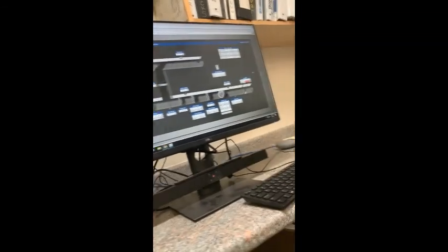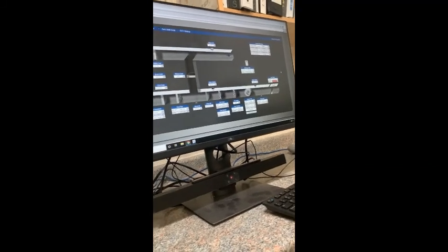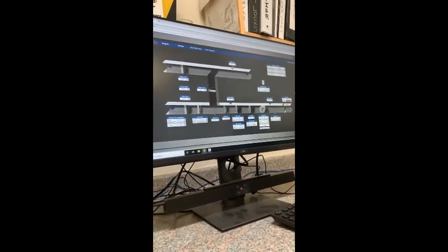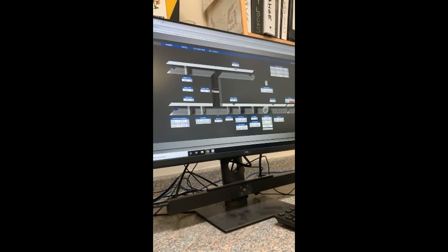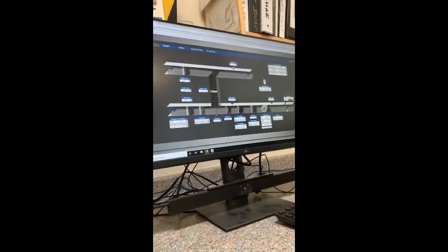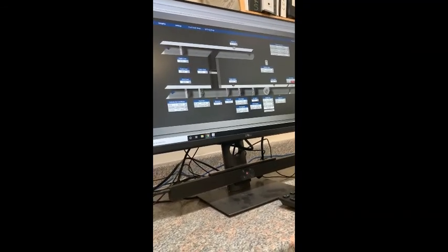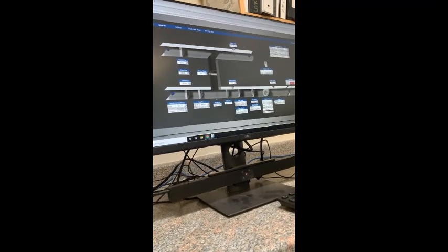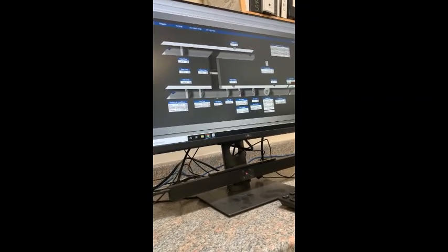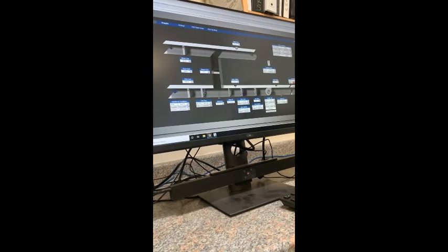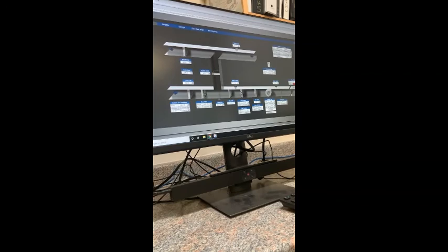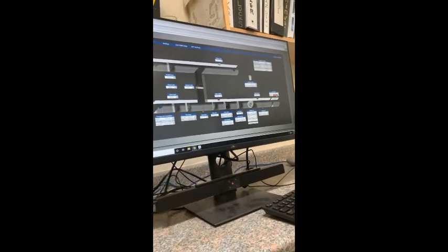The air handlers are all basically set up the same. They have an outside air flow, an economizer, return air. They look at building static. We increase to try to get building static up. We don't do anything to try to relieve the building static per the sequence. It's a single fan, so we can't really do anything besides open the dampers, a singular command. So we can see this one is showing the building static is slightly low.